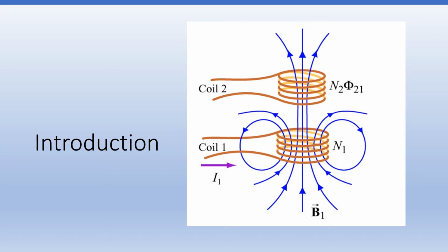Today I will be presenting a paper titled Mutual Inductance Estimation for Asymmetrical Coupler with Multiple Transmit Coils. In the coming slides, I will detail out the techniques we use to estimate the mutual inductance of a wireless coupler made up of 6 symmetrical transmit coils and a miniature receiving coil with a large transmit to receive diameter ratio of 15.